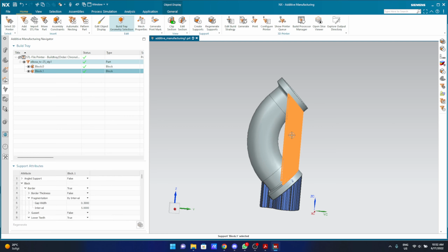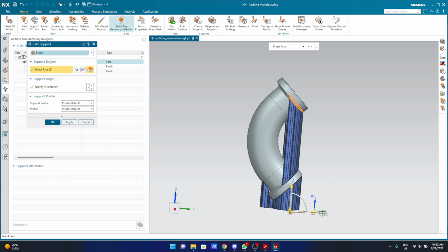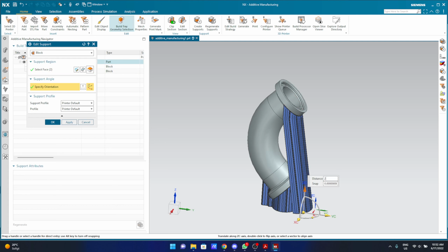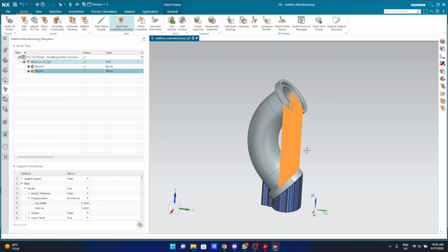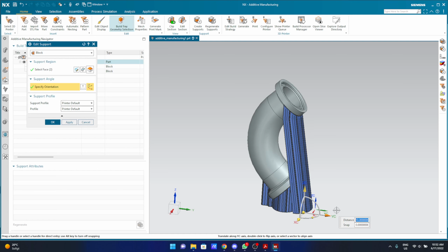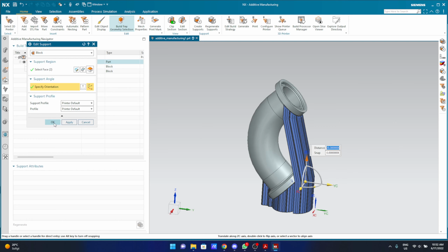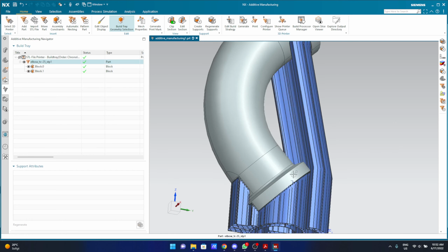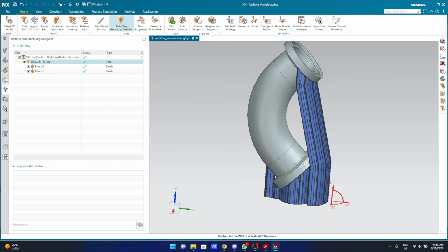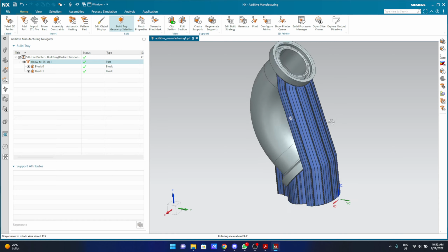So what I did was I just edited this. I moved it 10 mm ahead and 20 mm to the top. Click on OK. So now it won't rest on the pre-solidified part, won't cause reheating, and it is easy to remove. I'll just grab it here and pull it. It will just break here.